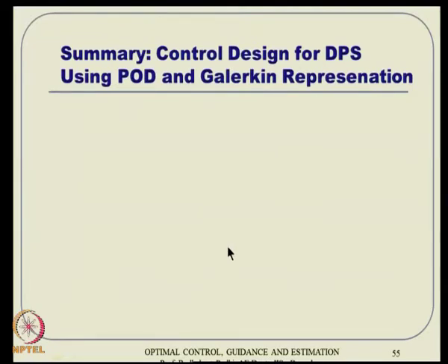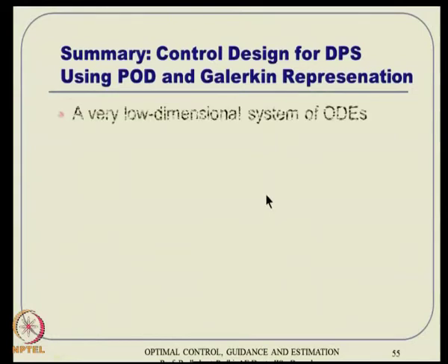So, a summary of this entire control design approach using POD and Galerkin representation. First of all, it results in a very low dimensional system of ODEs. Again, this entire way of handling PDE systems is to somehow have a representation as ODEs and then apply ODE control design philosophies. One way is to not bother about model reduction and simply go ahead and implement it in finite difference.